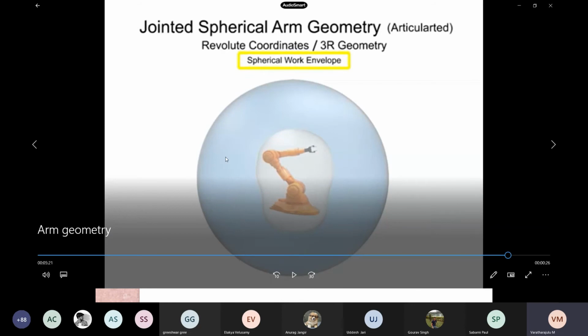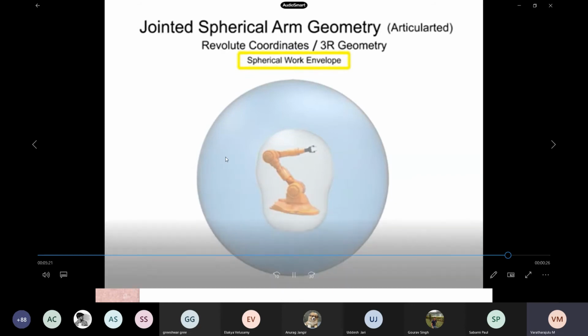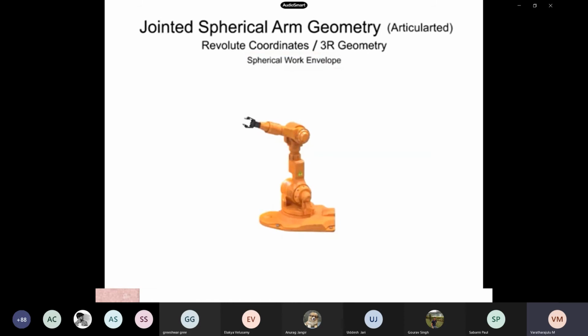The advantages of this type of work envelope are a robotic arm with very deep reach, minimal floor space use, and high positioning mobility of the tool end of the arm. Due to its mechanical complexity and the complexity of its controller, this robotic arm typically comes with a higher hardware cost and requires skilled technicians.